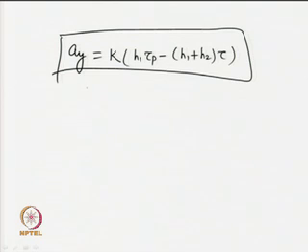So, whatever might be the area of the output signal, the real area of the output signal can be easily obtained using this simpler expression, which involves the parameters relay heights and a few measurements like first sampling, first zero crossing instant, second zero crossing instant from the beginning, which is considered to be 0, with the multiplication of k.